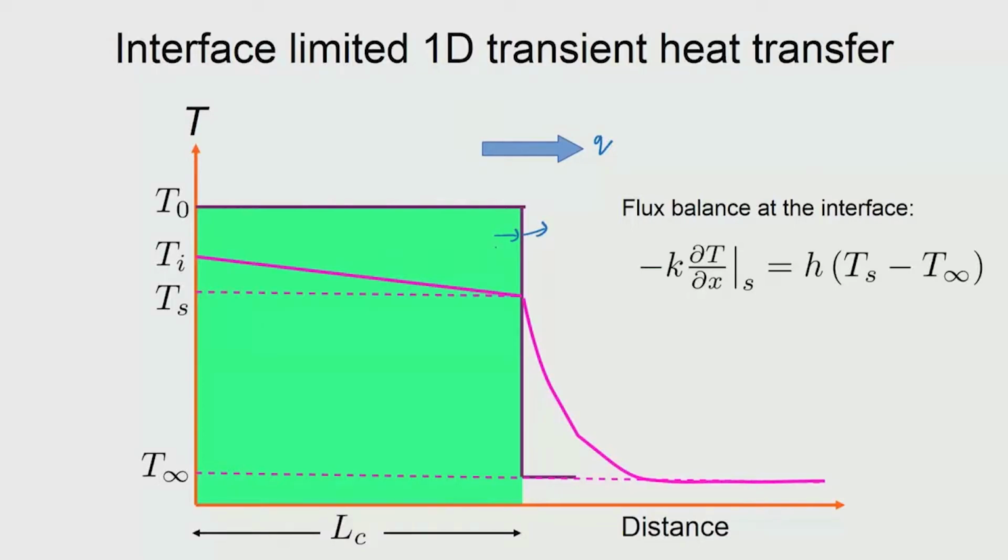interface. So, what heat flux comes up to the interface is given by the Fourier heat conduction equation, and then what is lost is given by Newton's law, and that is given here, and the cross sectional area A is cancelled out on both sides, because we are taking the rectangular case. So, we also mentioned that we are taking the rectangular case. Okay. And we now approximate the dT by dx to be just the differences of the temperature, because these gradients are anyway small. So, you can make this approximation.